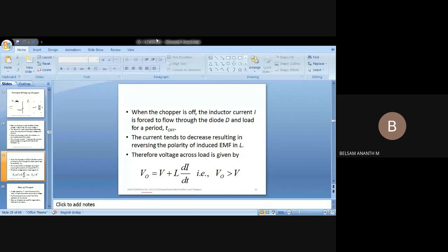There, you may have learned about state modeling of the equation. When you write the state model of any system, I am speaking about the electrical aspect. For example, I think you all learned system dynamics just one semester back. Suppose I have an electrical system with two inductances and one capacitance. Then what sort of matrix will I get to write the modeling of my system? A 3 by 3 matrix. So please remember, depending on the energy storage elements present, I will assume the state variables.